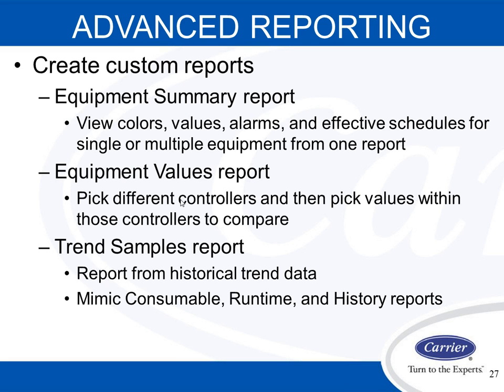Additionally, a trend sample report can be configured to get trended data into a report. The report interface allows you to select controllers, trends, and specify what interval of data you would like to view. It's also nice to save these, so if you are consistently looking at the same report, you can save that report, and then instead of going in and selecting the controllers each time, the report will be saved for future reporting needs.